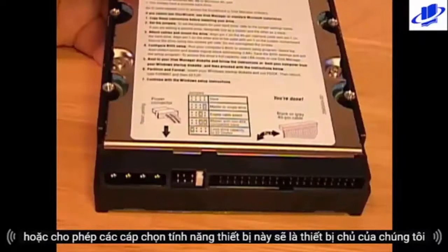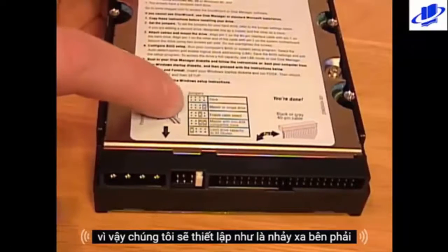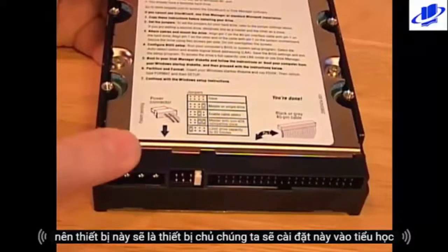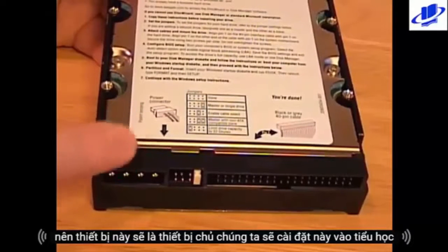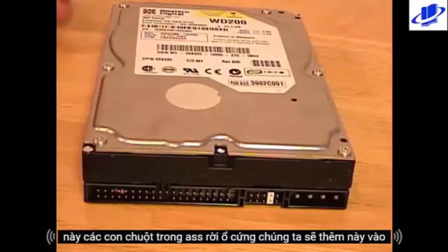This device is going to be our master device. So we're going to set it as the far right jumper. So this white jumper right here is already in the proper location. So this device will be the master device. We're going to install this on the primary controller. This device is going to be our slave hard drive. We're going to add this to the primary controller.